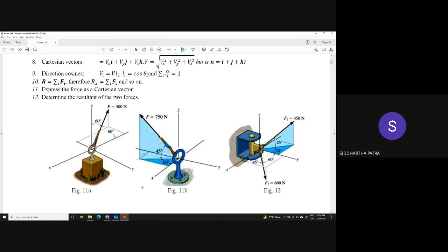The angle is always between two lines. It basically means that once you take the projection of that line on that plane, the angle is the one the line makes with its own projection. And that is actually the shortest angle that it makes with any line on that plane.